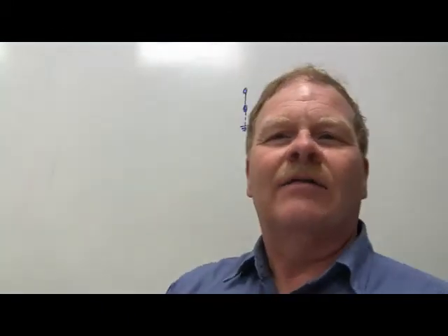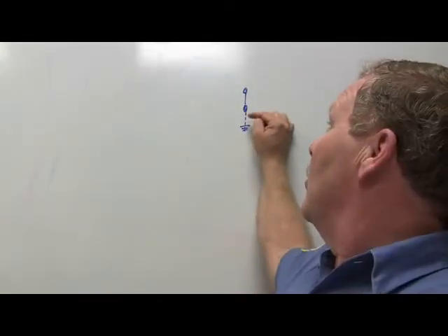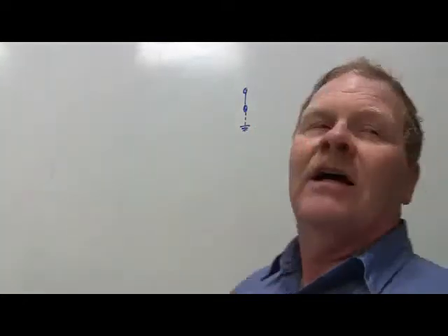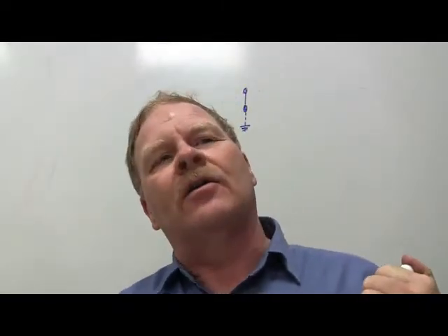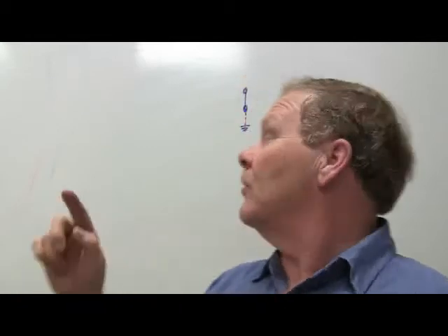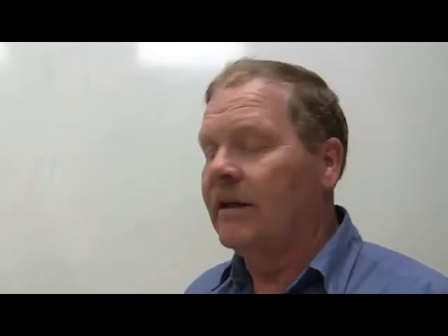See that? It'll have a little break, it won't be broken. What that's telling you is it's actually hooked to there, but it goes other places too. Now, why do you need to know that? If you're running another ground, let's say maybe that one is shorted to power or something like that, and you clip it out and you just ground this, a bunch of other stuff may go offline because you're not feeding that. So you need to watch for stuff like that and be able to understand it.